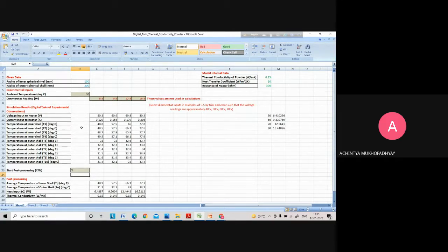So what should be the thermal conductivity at those levels of temperature that I should calculate and do it. If we know the variation of thermal conductivity of asbestos with temperature, say in a table kind of thing, then we can prepare a table where this heater input and the corresponding thermal conductivity values will also be changed.